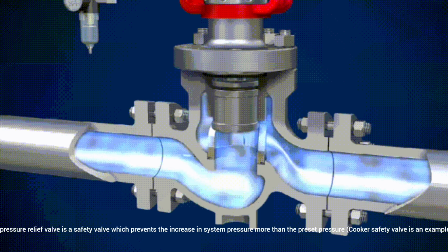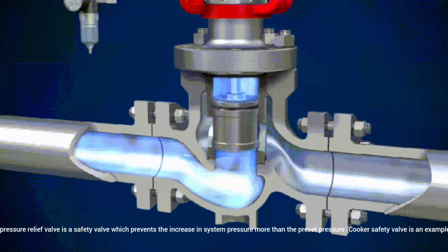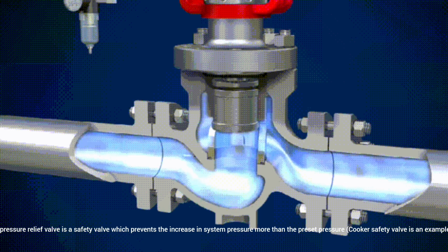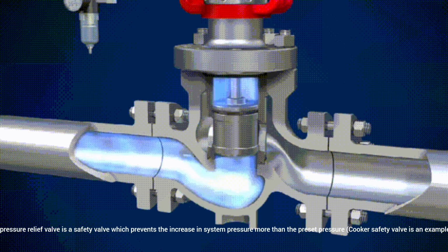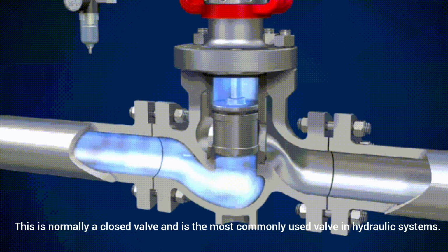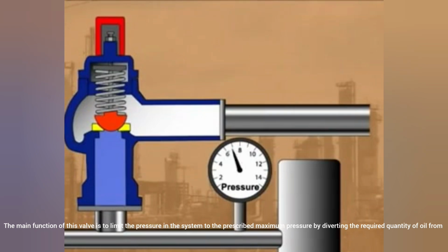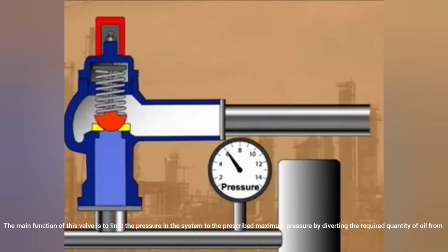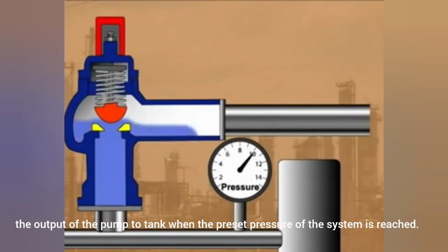Next, pressure relief valve. A pressure relief valve is a safety valve which prevents the increase in system pressure more than the preset pressure. Cooker safety valve is an example. This is normally a closed valve and is the most commonly used valve in hydraulic systems. The main function of this valve is to limit the pressure in the system to the prescribed maximum pressure by diverting the required quantity of oil from the output of the pump to tank when the preset pressure of the system is reached.